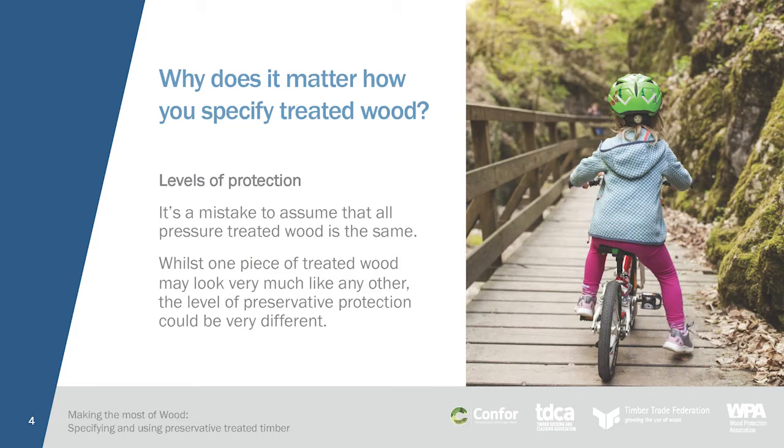However, it's a mistake to assume that all pressure-treated wood is the same. While one piece of treated wood may look very much like any other, the level of preservative protection could be very different. That's because national technical standards for wood preservation require that the loading and penetration of preservative impregnated into the wood is tailored to the desired end use.